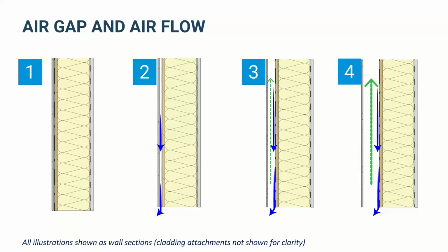Once you get into really big cavities, that can actually impact fire and smoke propagation. This is why we don't want gaps to be too big. Usually, 3/4 inch to an inch is fine in most cases, but larger than that, you start to get into more challenging fire considerations if you've got anything combustible in there.